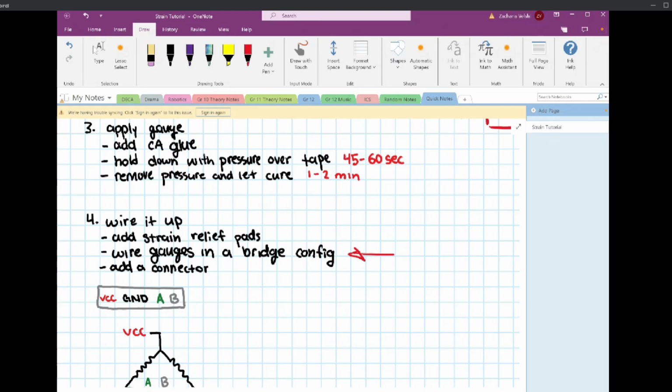It's one thing to resolder them, but CA glue is temperamental to really, really high heat, and these wires, because they're so thin, transmit temperature really, really fast, really easily, to the CA glue joints, and it doesn't have a fun time. Strain gauges, don't ask me how I know, also burn off really easily when you put a soldering iron to them. So you don't want to heat soak those.